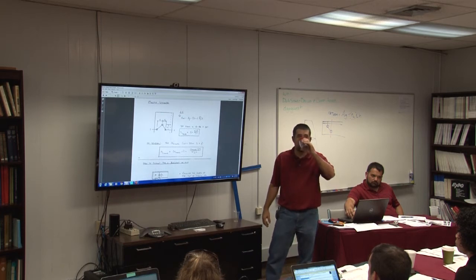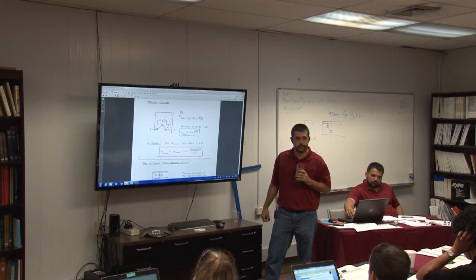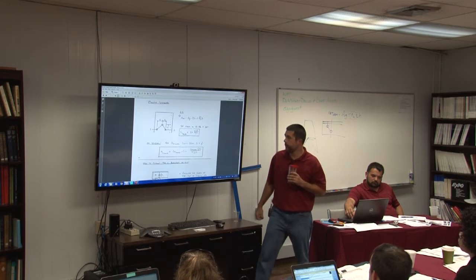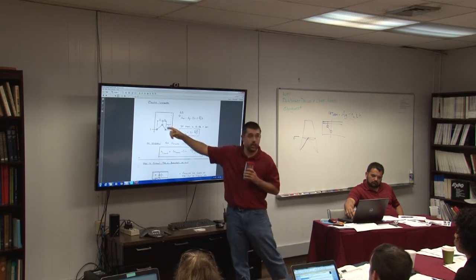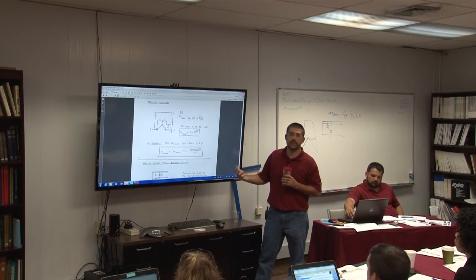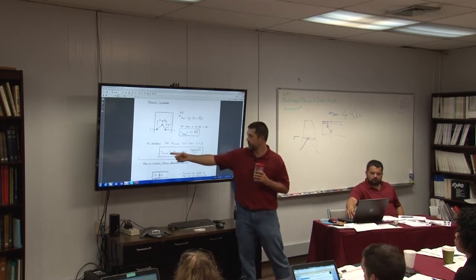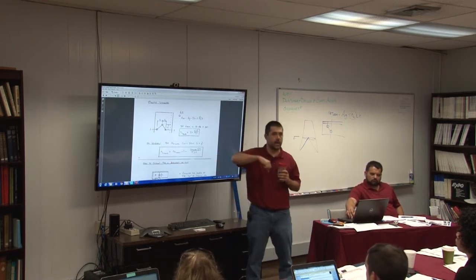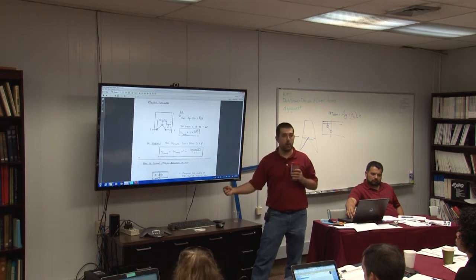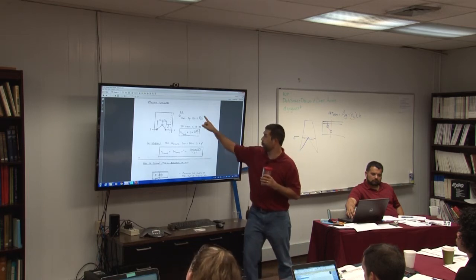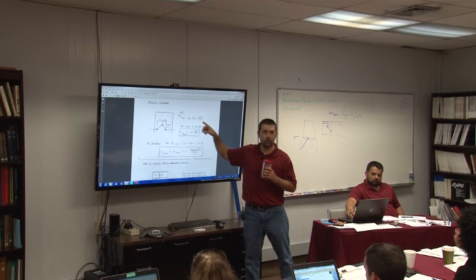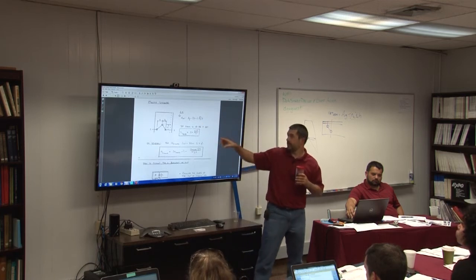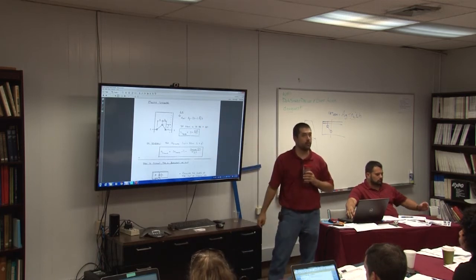It's all based off of the perpendicular dimensions from the leg or the angle. Yeah, you're talking about s and g? Yeah, and essentially what I'm saying is that if I calculate this number and put this number into Tower, the net section that falls out will be equivalent to the real equation. If I were to do the real equation with the staggers, the net area that falls out of that is equivalent.